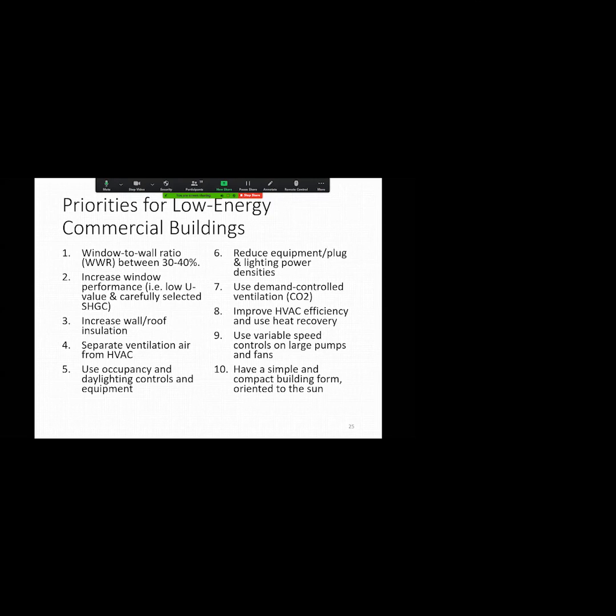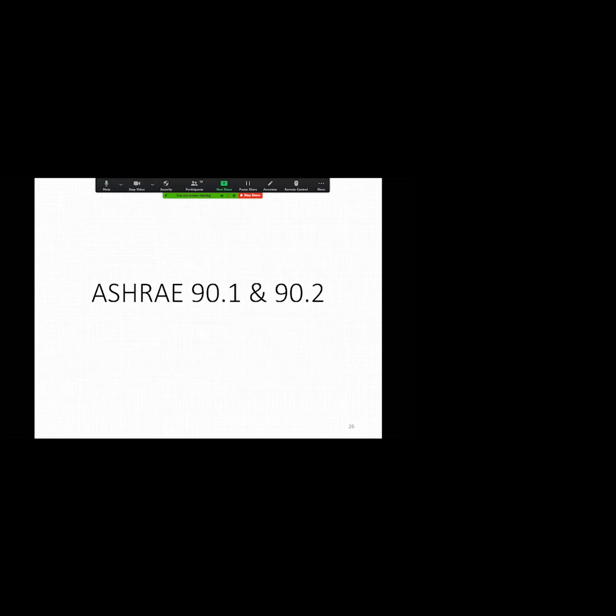And then, on the other sides of your building, if you have a ton of glazing on the northern facade in the winter and you're not getting any energy, you're putting that glazing there. It's the weak point. So you're going to be losing energy through that glazing. So, you want to pay attention which way your building's facing, which facade has the most glazing on it, and then pay attention to the ones that are not going to be getting the sun's energy and adjust accordingly.